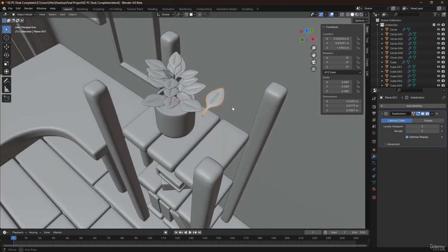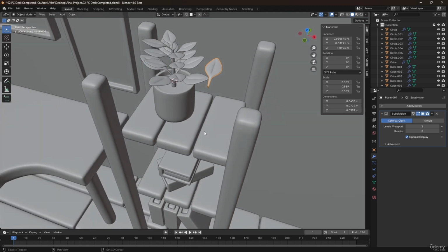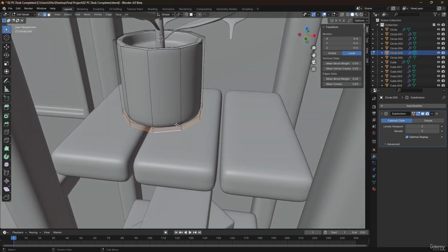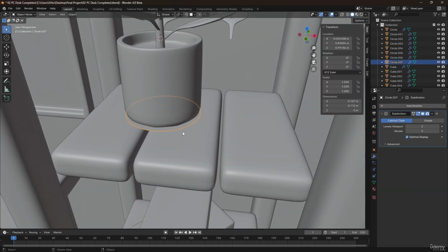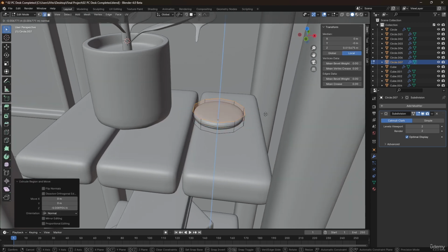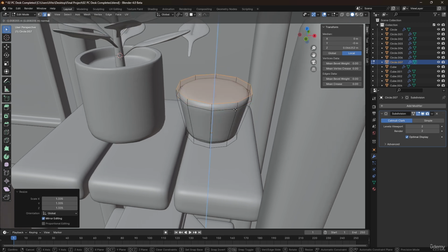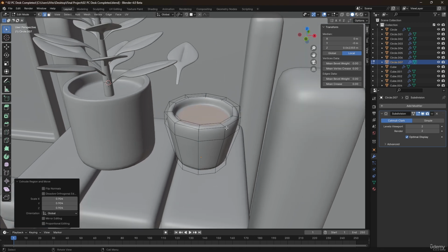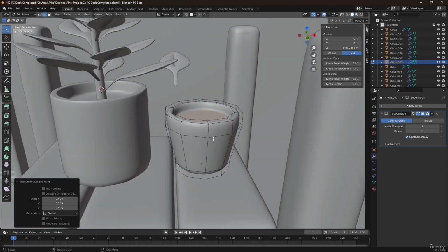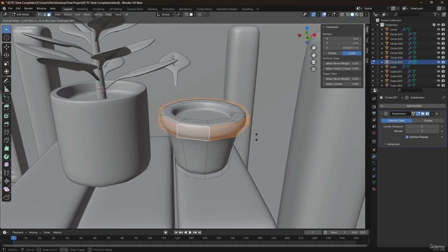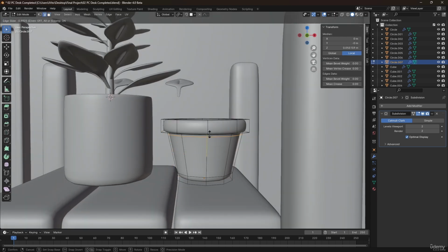And we're going to use this leaf as a reference for creating a particle system. And let's create a part here. And to do that, let's just take this edge loop. So in the edit mode, Shift D to duplicate. And then we're going to select that loop that we just copied. Scale it down. Extrude a couple times. And then we're going to inset the face. So we're basically just extruding and insetting faces a couple more times like that. And then in the face selection mode, we're going to extrude these along the face normal. And let's add a supporting loop cut there.